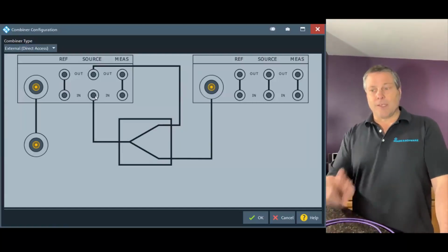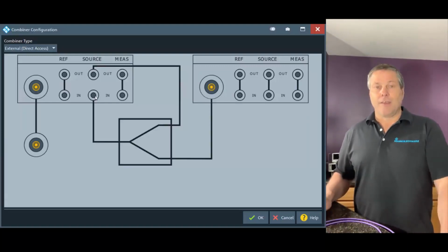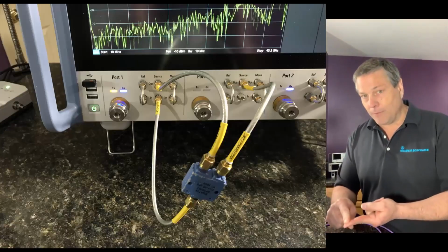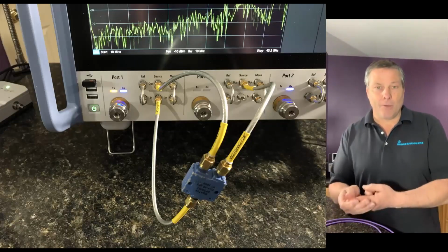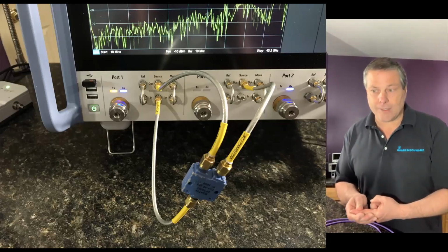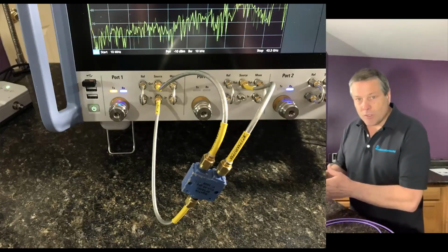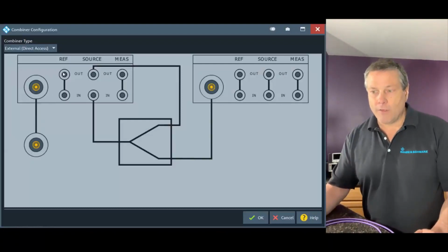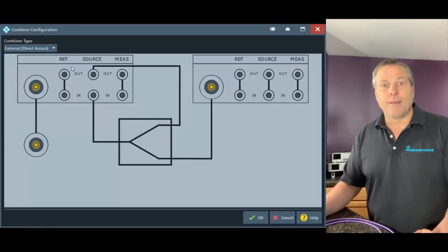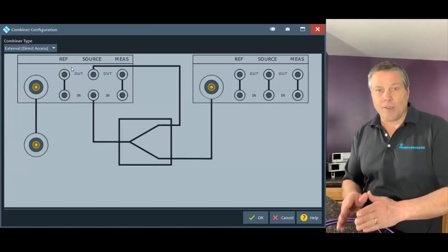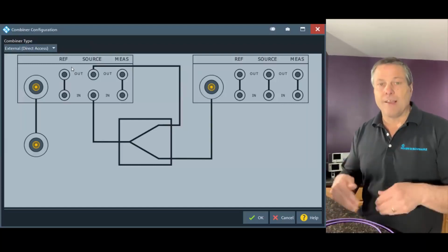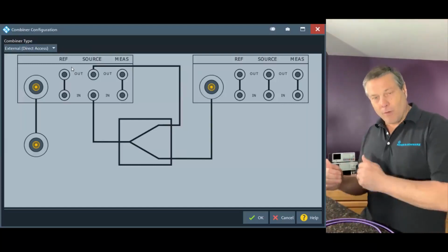so it can pass through the port 1 coupler. So this has two advantages, as I mentioned. It gets rid of the loss after the coupler, so I have better directivity and better ability to measure return loss of my device under test, and it allows both tones to pass by the one receiver, the reference receiver on port 1. So now a single receiver can measure the phase of the two tones, and this will be a little bit better than the previous way.